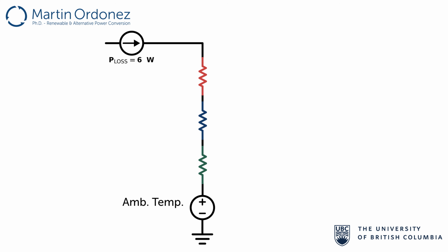Now, we can go back to our problem, which is the heat-sinked MOSFET. As calculated, we have the two thermal resistances, R theta SA, which is equal to 10.62 degrees Celsius per watt, and R theta CS, which is equal to 1.1 degrees Celsius per watt, since we have selected the silicon pad as our thermal conductor. Pay attention that in this case the MOSFET is connected to the heatsink, so we have to select the proper value of the thermal resistance between junction and case from the MOSFET datasheet.